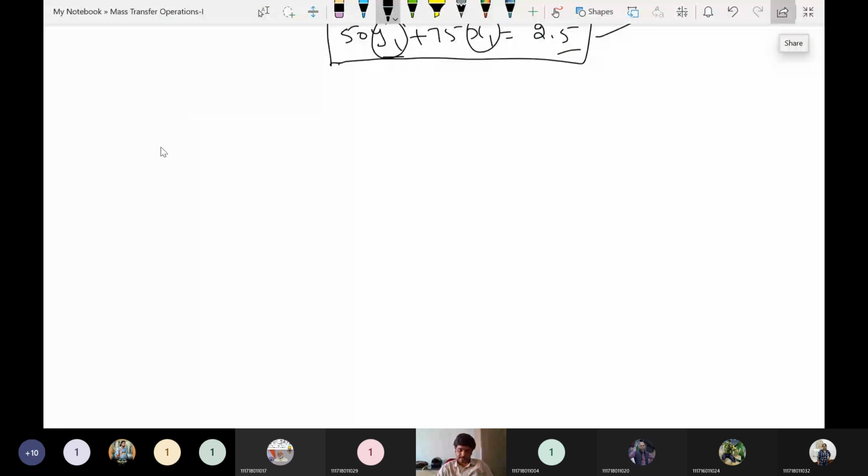So here, consider this. This is stage one, then this is stage two, and we can break it down until the final stage has been reached, NP, the NPth stage. The notation scheme which we applied for the single stage is the same here. First we are giving some feed here, with a mass fraction of solute YF, and the inert mass ratio will be NF here.